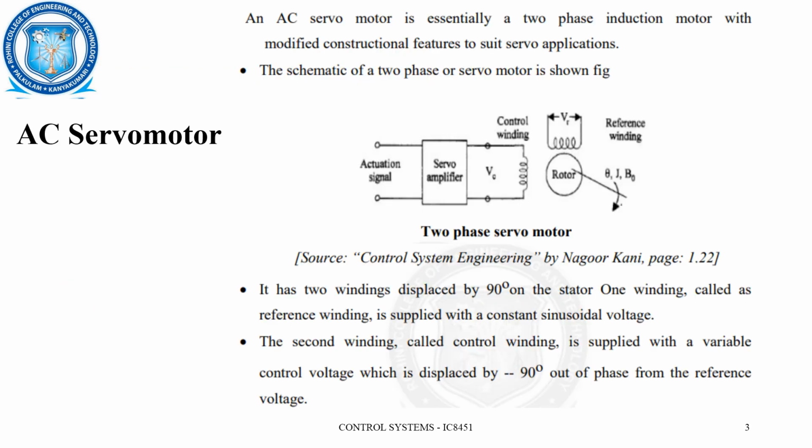A servo motor, normally a servo, the word represents the position. So the servo motor is nothing but we are finding out the position of the motor. In the sense, the rotor position is sensed. So we are sensing the position of the rotor, and then that will be provided as a feedback to any control system, and finally the motor will be made to operate efficiently. So this is the process which is carried out, called the servo mechanism, in these DC and AC servo motors. Let us see about the servo motor of AC type first.